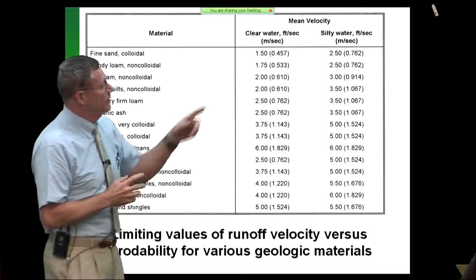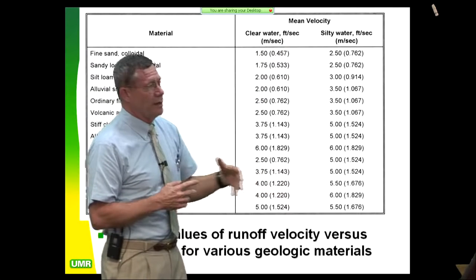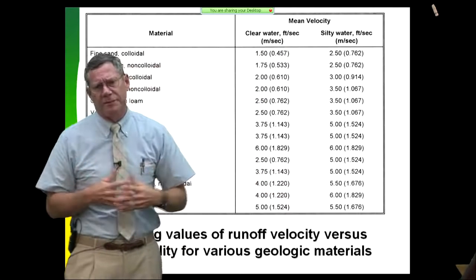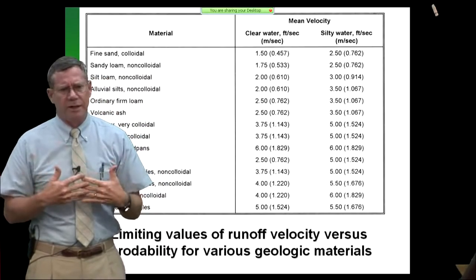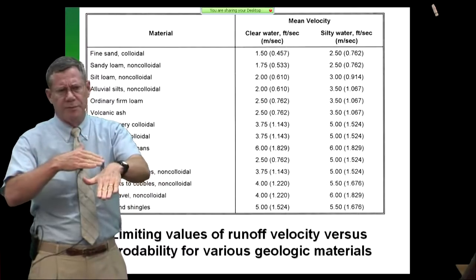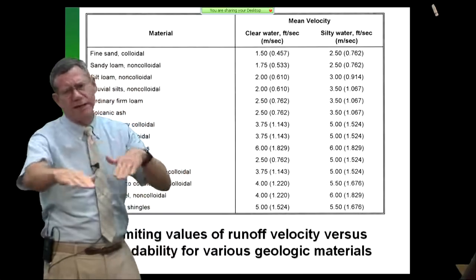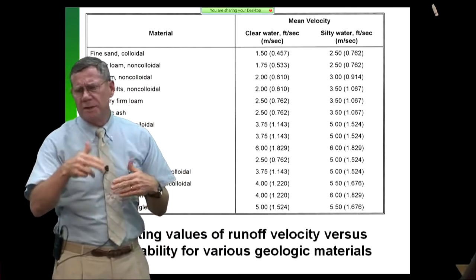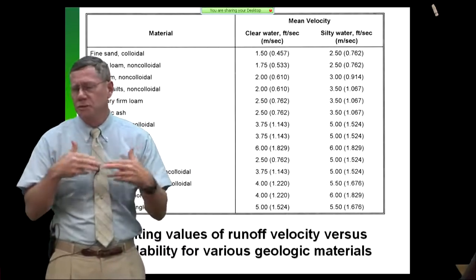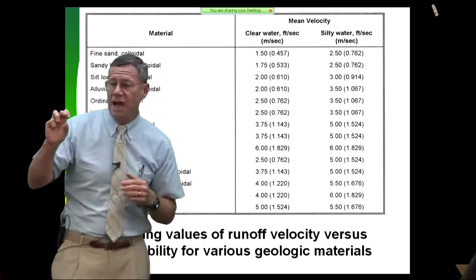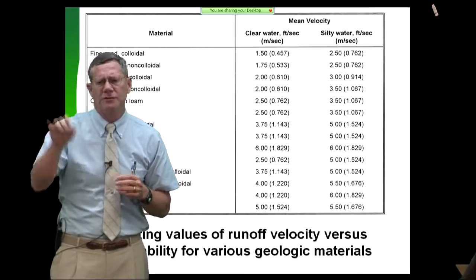Now why this is important as practicing engineers is when you try to protect something by putting in riprap or gravel or something like that, you have to realize that velocity is your enemy, and velocity is going to tend to build up on a slope, such as on a dike. About 2/3 of the way down a 300-foot long dike, you're going to reach some critical traction velocity. We're going to start cutting the root mass, and maybe the roots are just an inch or half-inch deep, since fescue grass isn't very deep rooting. Once you break that root mat, whew, you're off to the races.